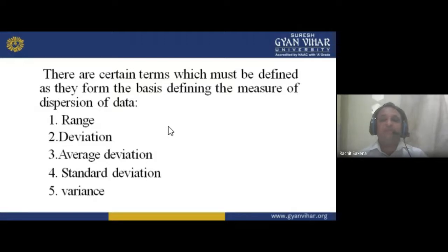For example, if the measuring instrument has to work at 20 or 25 degrees centigrade, then you have to try to make it 25 degrees every time, wherever you are doing the measurement. So you have to take some precautions at the time of measurement. These are the elimination of error.